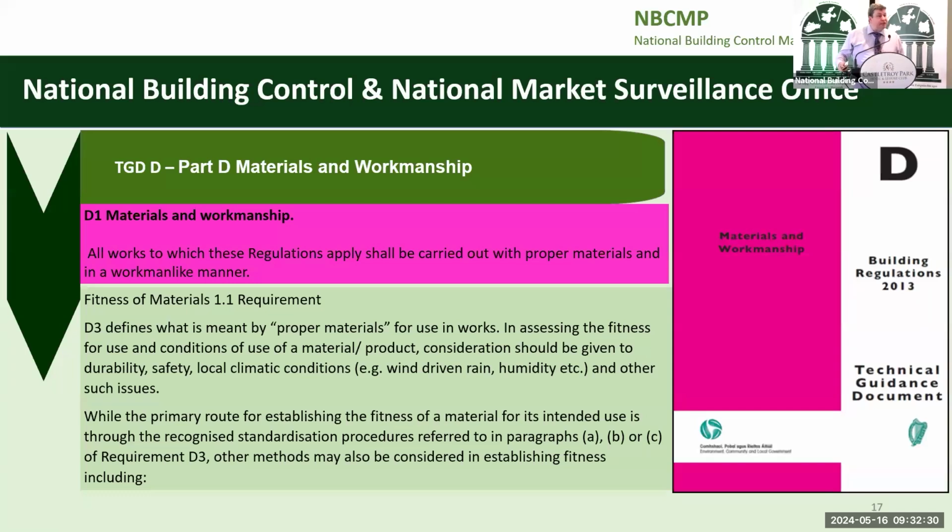Like PVC is affected by UV light. Like our internal plasterboards, you can't use that on the outside because they're organic and they absorb moisture, and then when they get wet, they expand. So it's understanding the limitations and the use of the materials and how you can design them into the building in a way that they can be used, but also how you address that maintenance to the end user going forward.